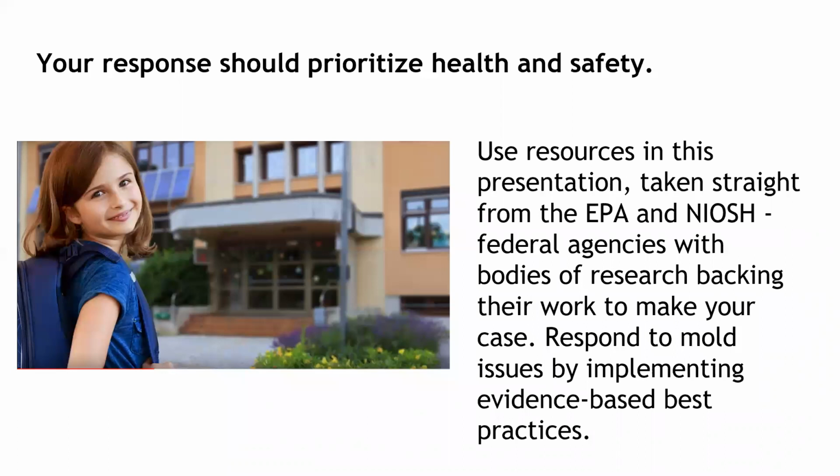Another thing I want to caution folks again is using ozone generators or any ozone generating air cleaner. The EPA specifically has guidance that says that used with manufacturers' instructions, it's not enough to get rid of mold. It's not enough to get rid of indoor air quality contaminants. And if you use it not following the manufacturer's instructions, you need to pump more ozone, which we know is a health risk. It's something that has acute effects.